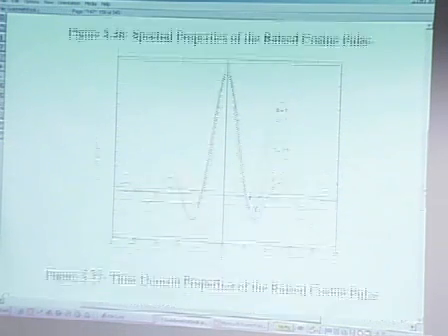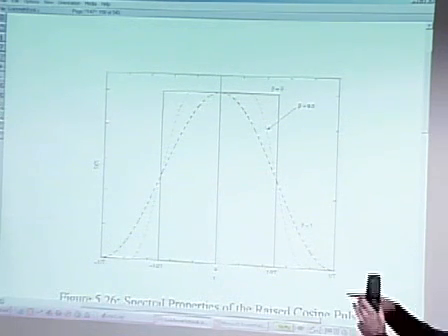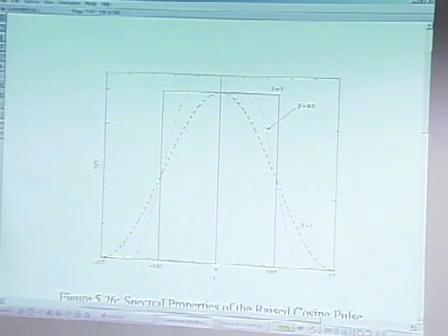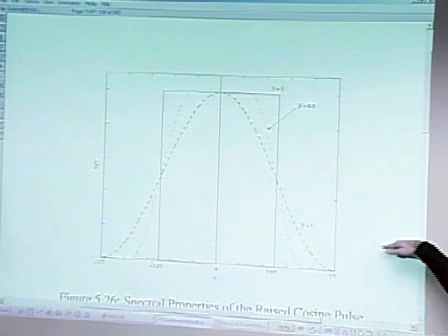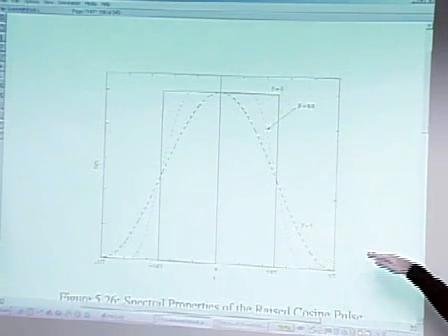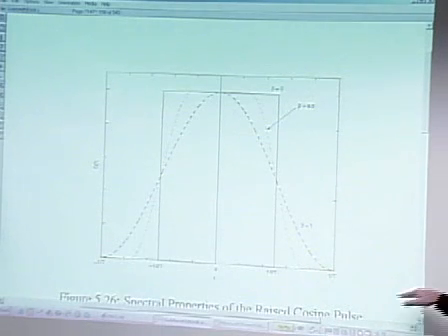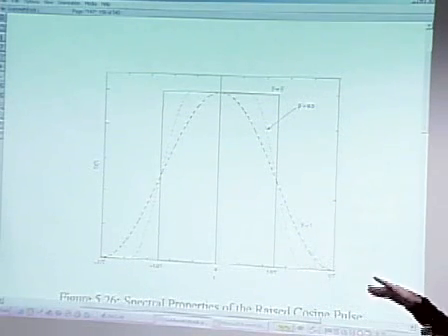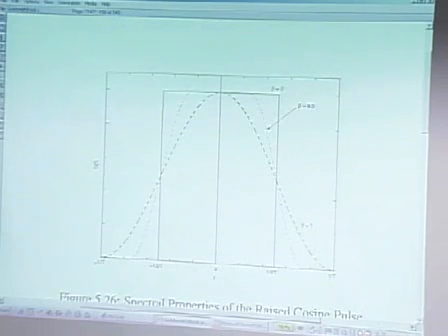So what happens is that this very nice shape that goes to 0 and then stays 0 forever, when you window it in the time domain to make it finite, causes some lobes over here. So there is some spectrum regrowth, it's called. So this becomes non-zero for some frequencies over here. But it's pretty weak. As long as you're careful with the windowing, these lobes are pretty small. So it's a small effect, but it does break this perfectly nice shape in the frequency domain.